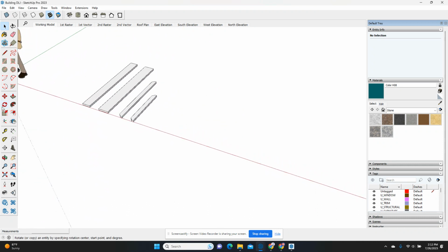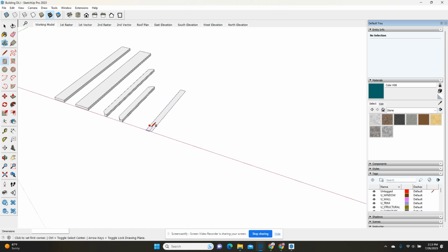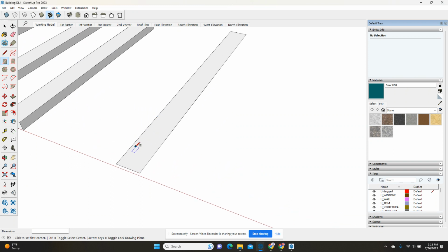So I'm going to draw it using the rectangle command. Pick close to the yellow line, go up in this direction, type in 3.5, comma, this time we're going to type in 42, and hit enter. So there it is right there. Okay, now what I want to do is I want to cut this off right here so that the angle between this line and the line I'm going to draw is going to be 54 degrees.